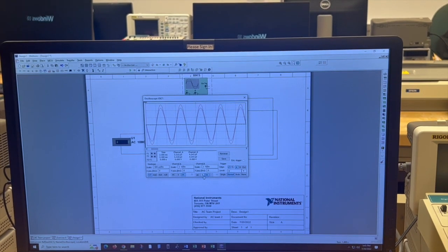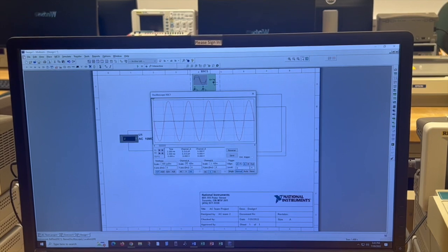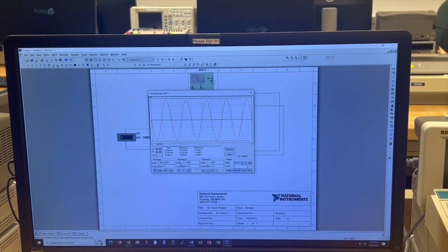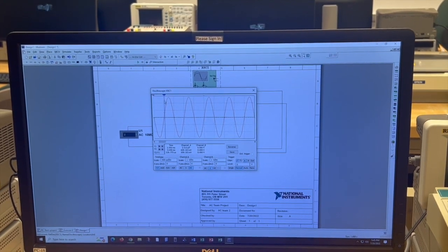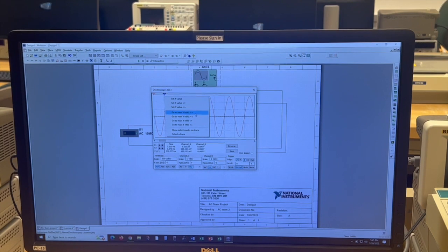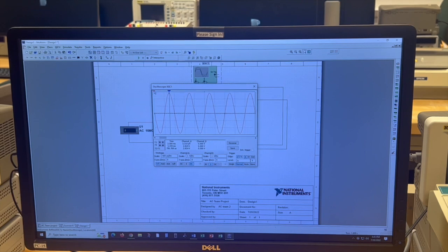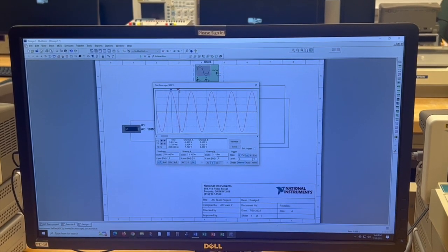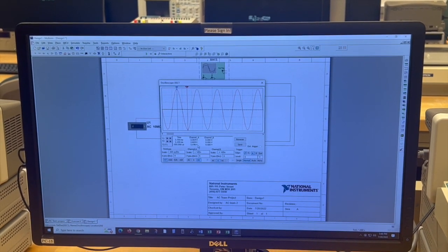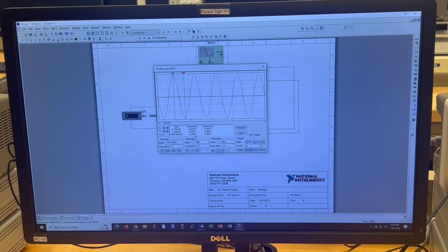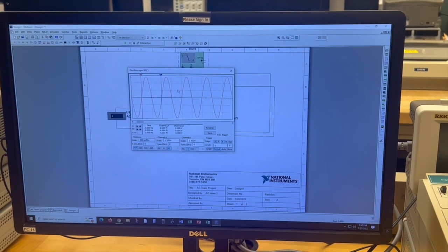We're turning off channel B to focus on our channel A, which is reading our voltage source measurement. We're going to measure our peak to peak first, moving our 2 scale closest to the peak and setting the Y maximum value to the right, setting our Y minimum to the right as well, and we will get 5.648 volts.